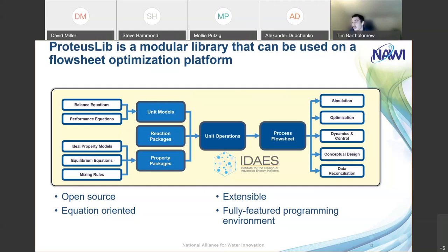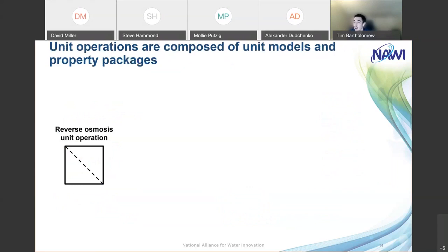And so where ProteusLib fits in this is that it is the collection of unit models, reaction packages, and property packages that are water treatment specific, so that we can do all the other capabilities of simulation and optimization with water treatment processes. So to describe this a little more, I'm going to walk through one unit operation example,